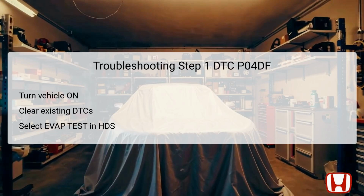The first step in troubleshooting DTC P04DF involves problem verification. Begin by turning the vehicle to the on mode without starting the engine. This action powers the vehicle's electronics, allowing necessary systems to initialize.